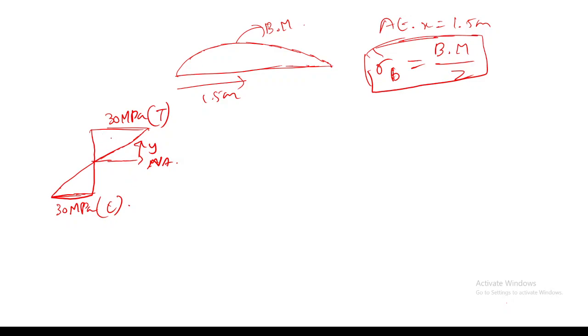If possible, for this cross section alone, maybe you can find out the average bending stress, and then find out the tensile or compressive force which gives the same effect. The effect should not change when you are substituting in terms of average bending stress. What I mean by effect is the loading conditions or the total force conditions, that should not change.